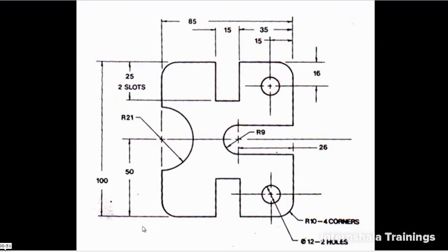For that, you have to go through the figure and locate the maximum dimension. The maximum dimension is 100 units in this. So you have to define the upper right corner in such a way that its value is above the maximum dimension to be plotted. Since the maximum dimension is 100, you can give a value something like 125 or 150.